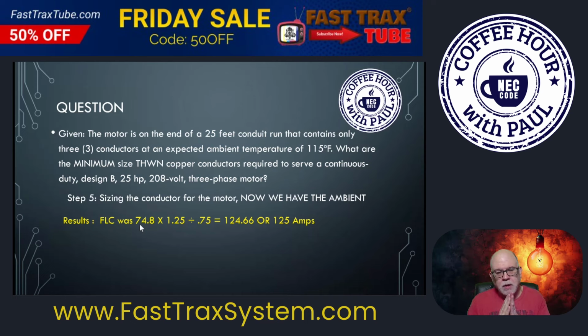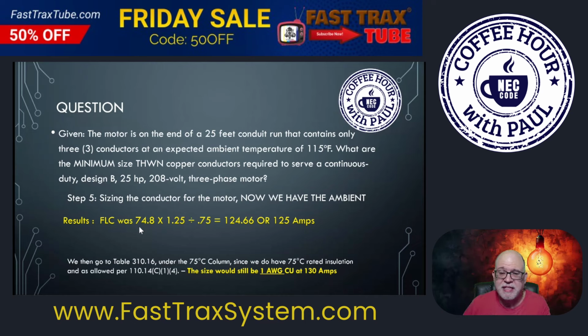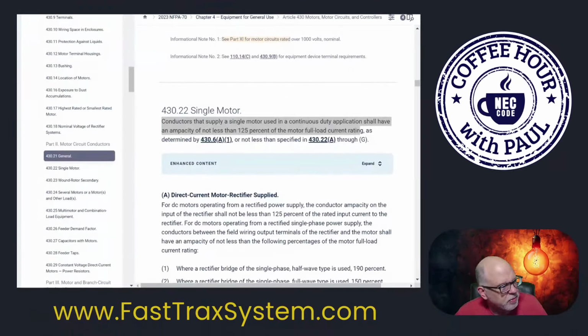So now, where would we go? We're going to go to 310.16, and we need to go to the 75-degree column because that's our terminal limitation. I mean, that is what our conductor limitation was because we didn't use 90-degree rated conductors. We used 75. So let's go to the code really quick. I'm going back to 310.16, and let's get to the ampacity table. I'm going to throw this up on the screen as big as I can make it.